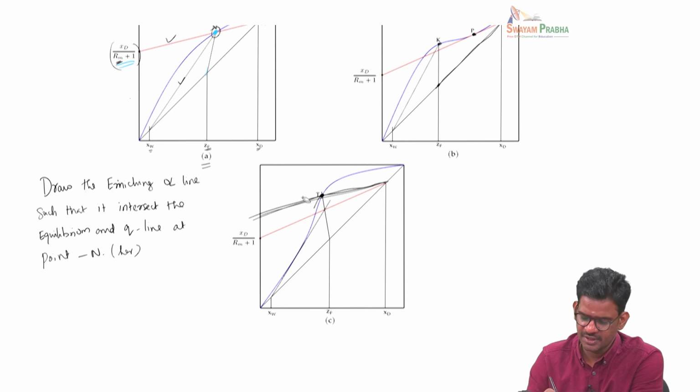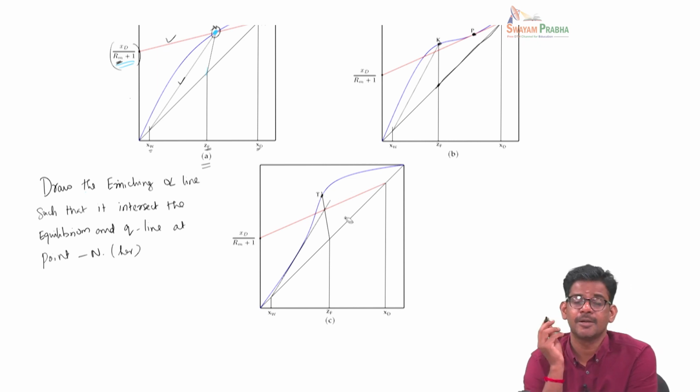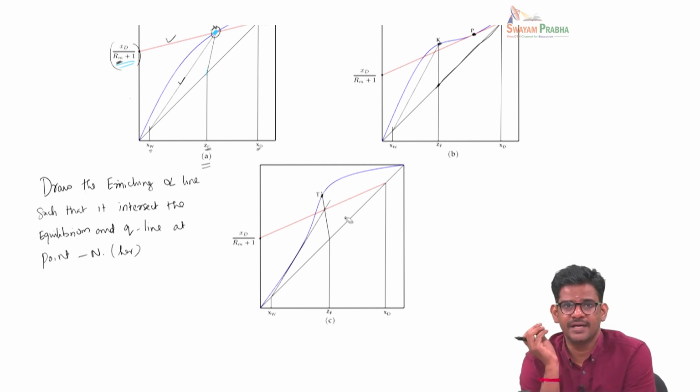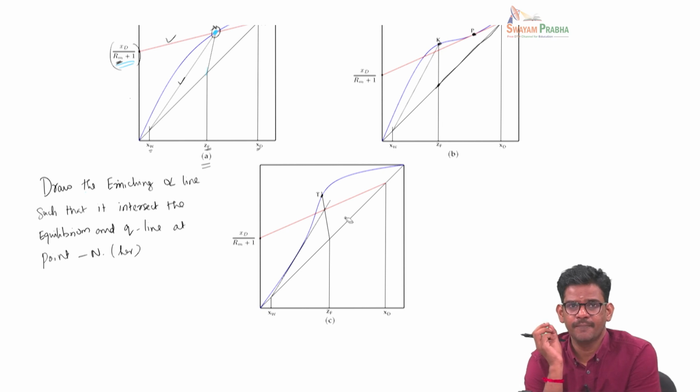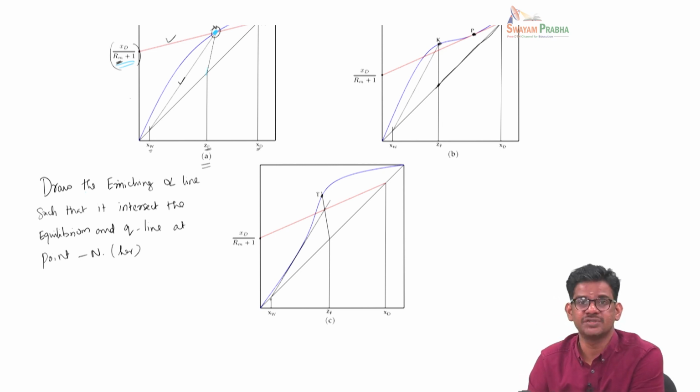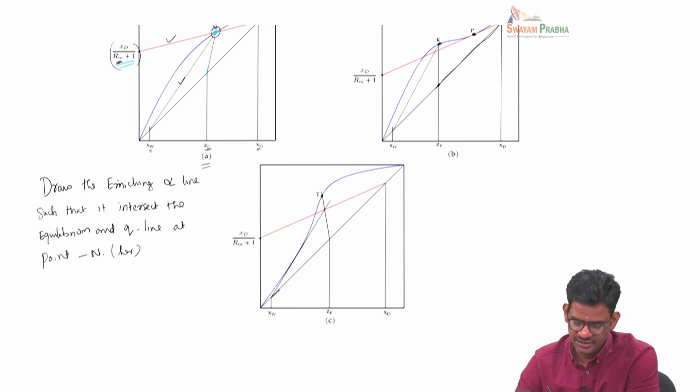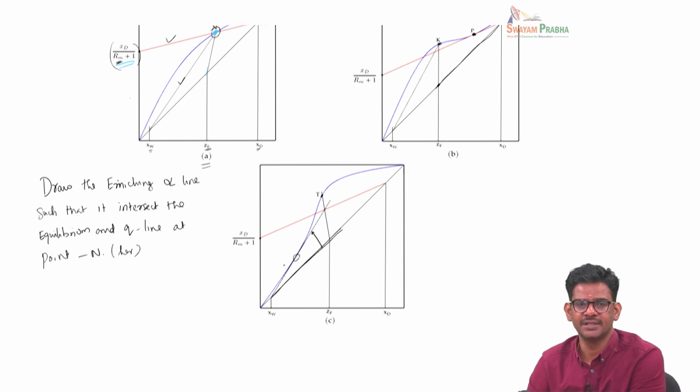So here in this particular case, the minimum reflux ratio has to be obtained from the exhausting line. Here we start with the exhausting line at the 45-degree line, and then we keep on increasing the slope all the way here, where this operating line just barely touches the equilibrium line at this particular point.